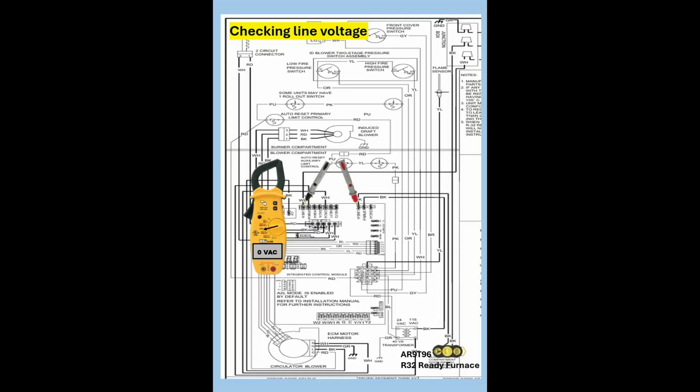And you see checking line voltage, you have to have your door switch, something over your door switch, magnetic stud finder, or however you do it. And check the voltage at line N and line H. And here's line H and here's line N, the neutral.